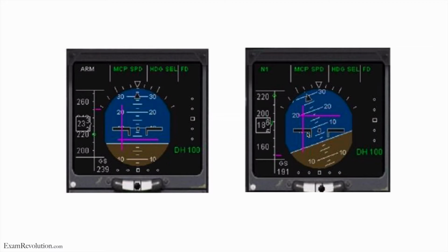And you can see here the aircraft is banking to the right again. So what is going to happen here? Well, we have a line that's to the left again, and now the bar is at the top. Okay, so that means we have to take this square and we have to put it there. So that means we have to make wings level or turn a little bit to the left because the bar is saying come to the left. And also we have the horizontal bar there, which says you need to pitch up. So you must probably be flying too fast. It looks like you've selected a speed in this case of 155 knots. You're flying 185, right? So you're 30 knots too fast. So obviously the bar is going to tell you to pitch up, right, until you get to 155 knots. So that's how the flight director works.